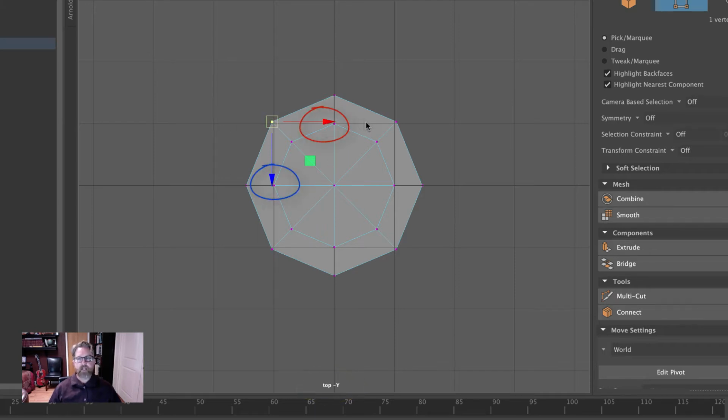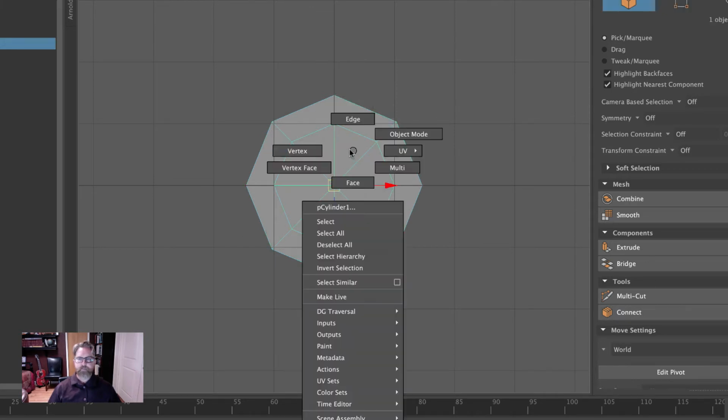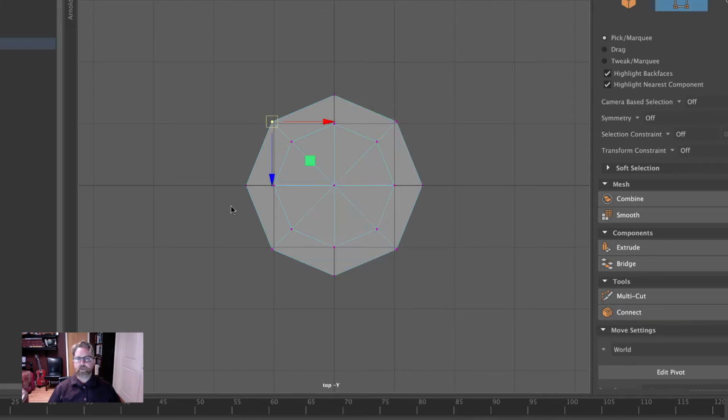And so a better technique, at least a better technique for beginners, is don't touch the thing that you're snapping. Touch the thing that you're snapping to. Right, let's start again. Got my object. I'll right click, choose this vertex. I'm not going to touch it.